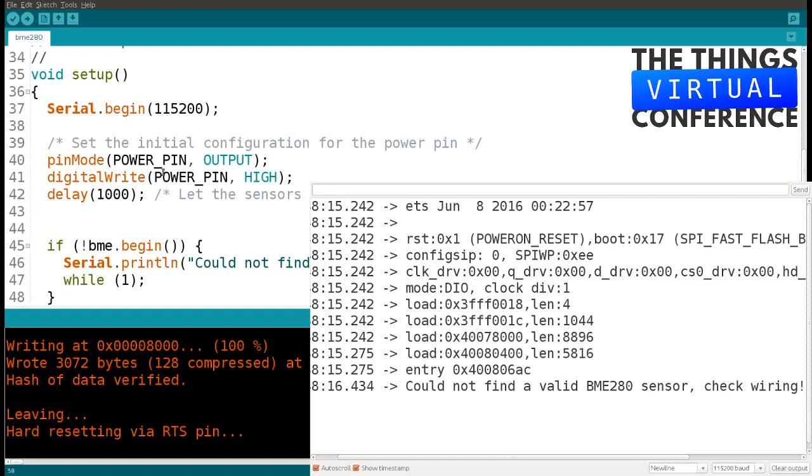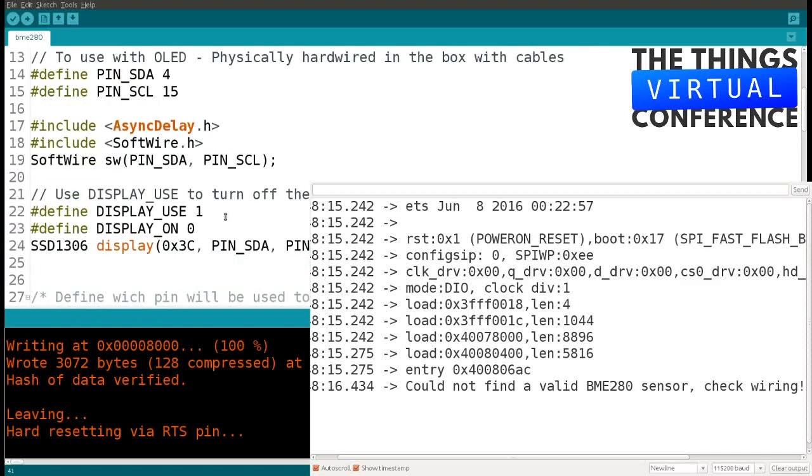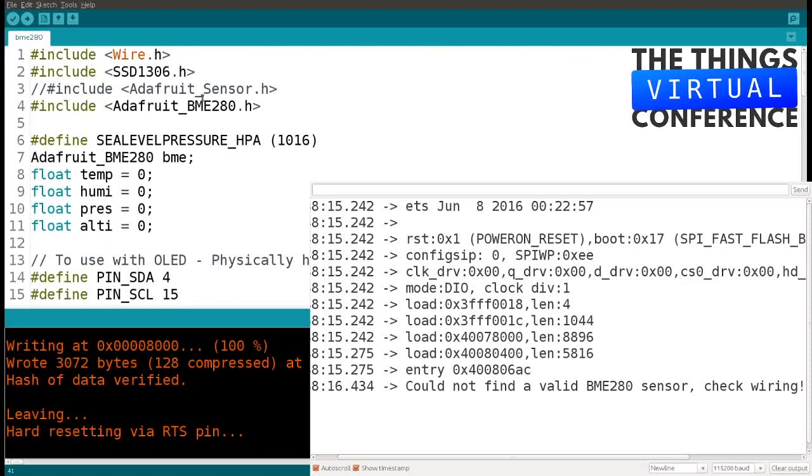These BME, like the I2C sensors, like the one-wire bus, the I2C sensors, they have numbers, they have IDs, and if you use the Adafruit library, they are not defined inside your program. They are defined inside this file. So I have now to find this file and check that I have the right ID inside this library before I can flash it again and see if it works. It's normally that problem.